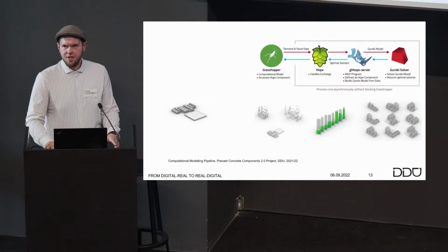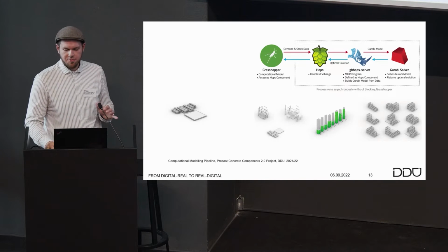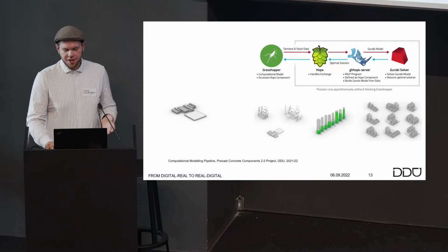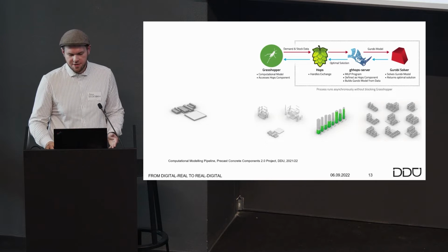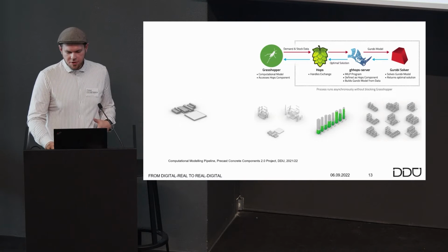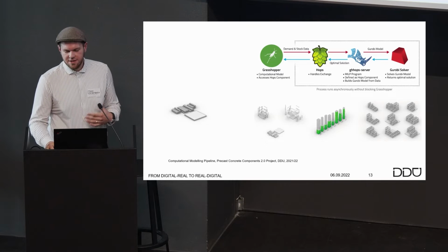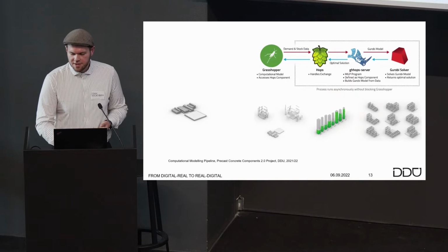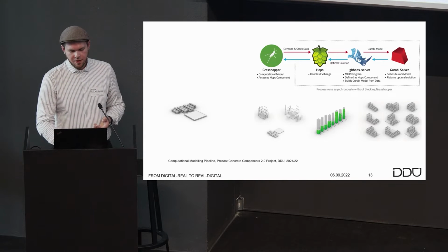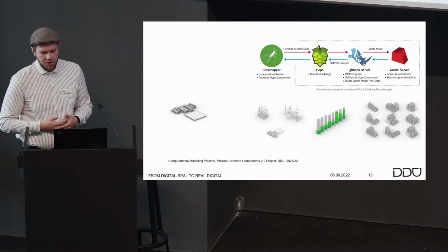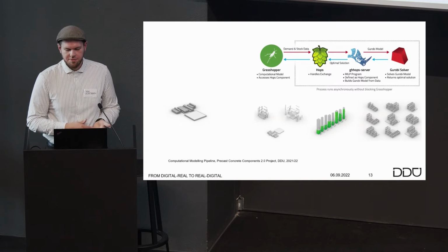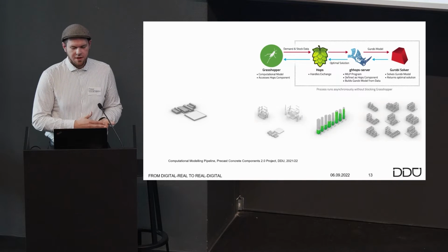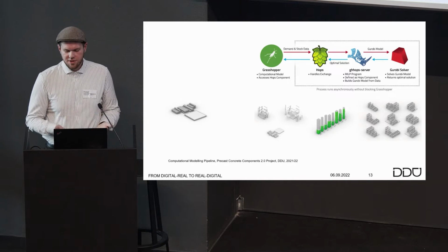Currently, we are using mixed integer programming to compute these optimal matchings using the Gurobi solver, as this allows us to include differentiated constraints into the optimization process. So for example, structural constraints, transport routes, as well as data from lifecycle assessment can be included into the decision process and thus inform the optimization. And through that, we are able to overcome the limits of conventional matching algorithms, such as the famous Hungarian algorithm, which does not allow for additional constraints, but instead only operates on the single cost value.